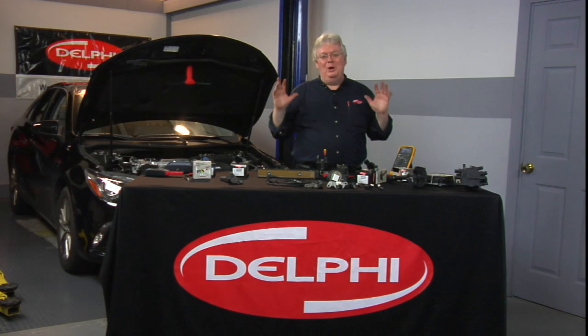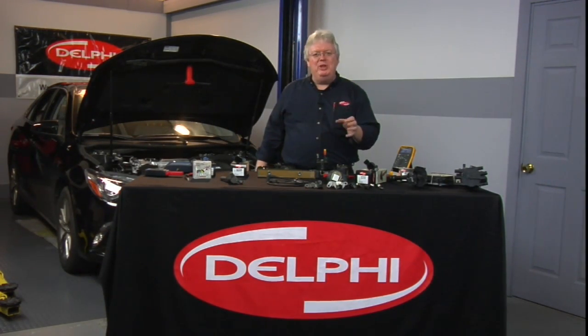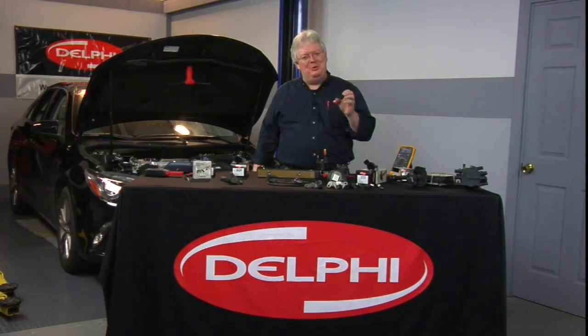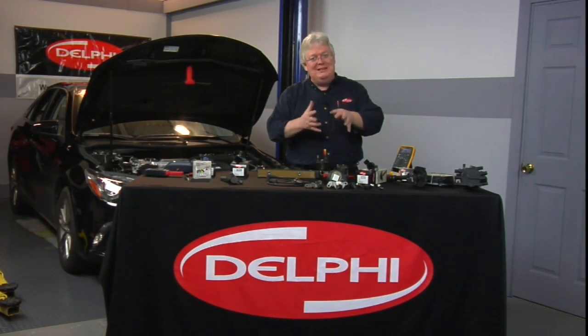Ignition testing on a workbench has been a tradition since the early days of ignition. If you're an old enough tech to remember the old oil-filled tower-shaped coils, it's very simple. You want to measure the primary winding resistance to make sure you didn't have an open, because it's not going to work if there's an open circuit. It had to be a complete circuit, an ohm or two typically were some numbers you'd see. The secondary winding would be between one of those primary winding towers where the small wire would go to from the points, or on newer cars, the ignition module, and the secondary output. So that was the connection for one side of the secondary.